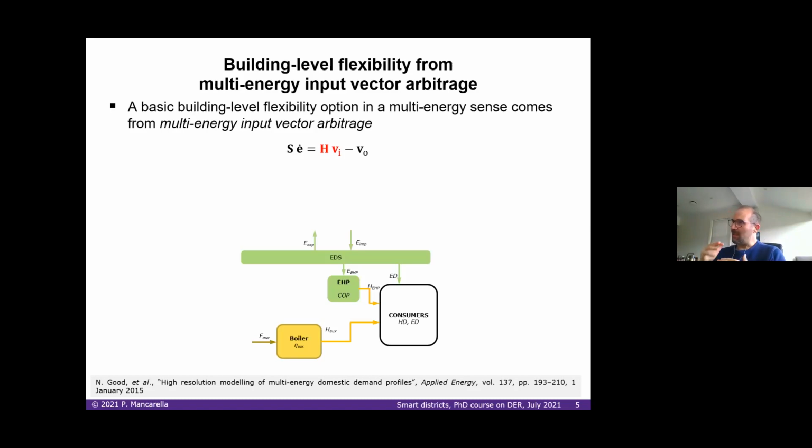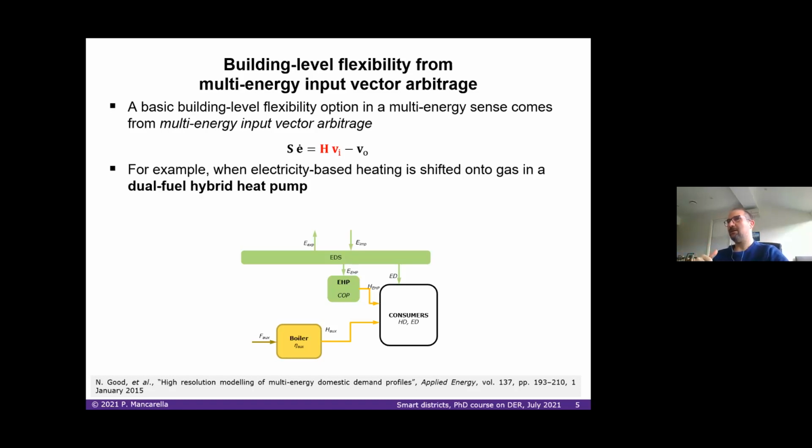Therefore, in order to meet the heat demand when it's really cold, you will need a gigantic heat pump with a massive impact on the bill, on the electricity infrastructure, and all that. So it may be more beneficial actually to introduce a small auxiliary boiler to top up the electric heat pump when it's really cold.